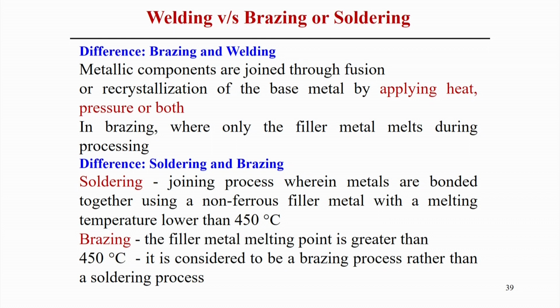The basic difference between brazing and welding is that in welding, the metallic components are necessarily melted and then they fuse together after solidification. But in brazing or soldering, we generally apply heat and melt the filler material, but it is not necessary to melt the base material. So, in that sense it is different from the welding process.